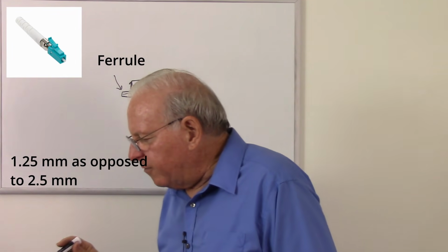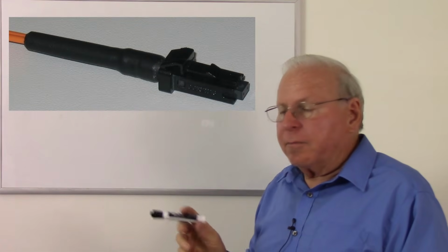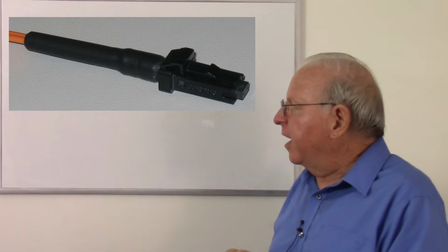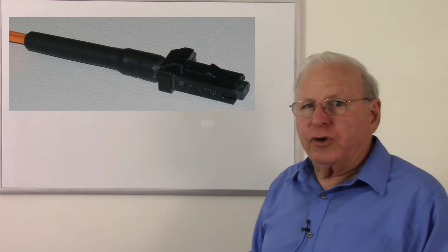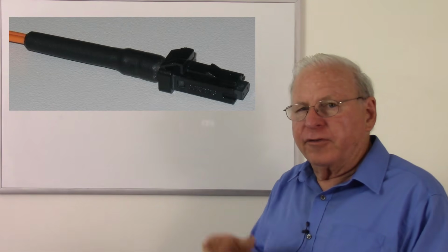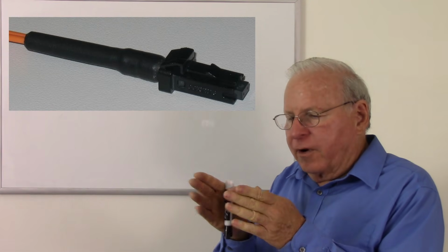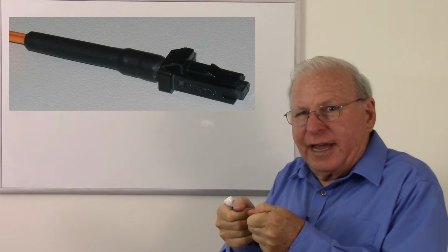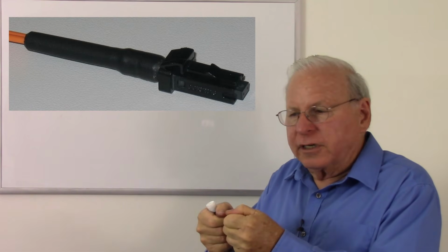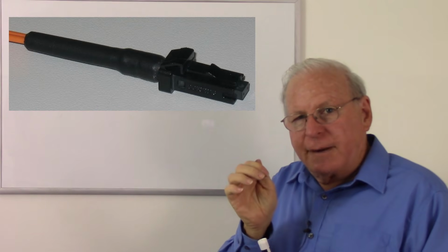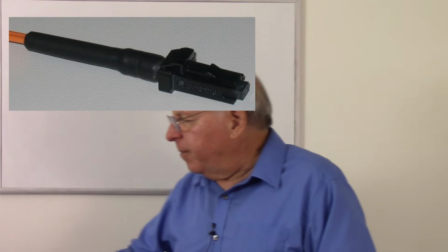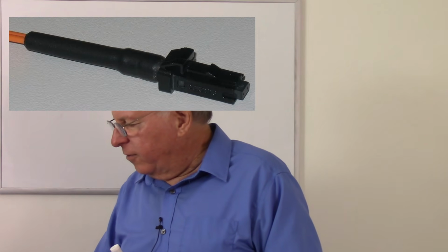And another connector we have is the MTRJ. That stands for multiple termination, I believe. RJ comes from its resemblance to the RJ45 connector. This is typically used for duplex connections, so there's actually two fibers in here. Plug it in, and you get both transmit and receive, unlike the SC connector, where sometimes you'll find two SC connectors connected together with a clip, and you use them both at the same time, or they have to be used one at a time. The MTRJ: two fibers, transmit and receive, one connector, click it in. I've actually never seen this in the wild, but apparently it's popular, so I added it here.